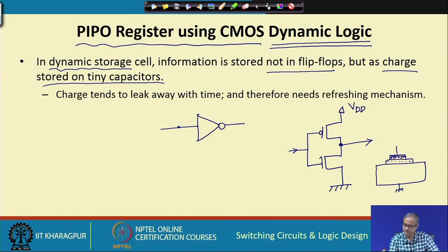There is one terminal this side, one terminal this side and an insulating region in between. So, as an equivalent circuit I can say that it is as if it is driving a capacitance. When the input changes from 0 to 1, it is as if I am charging this capacitance, and when I change it from 1 to 0, as if I am discharging the capacitance.